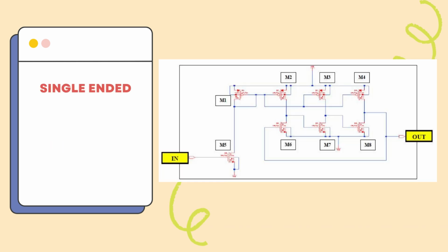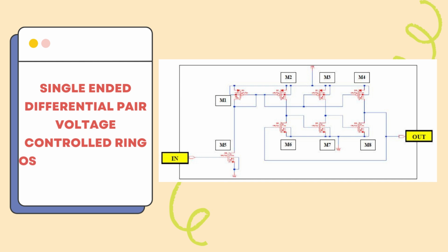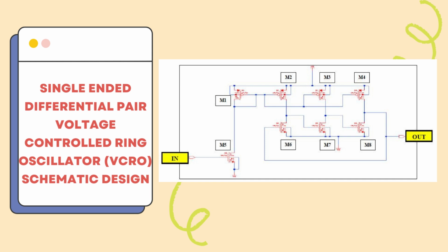Let's now explore the last key component, the voltage-controlled ring oscillator, or VCRO. Looking at this figure, you'll see its transistor-level schematic. This oscillator is absolutely central to our PLL's operation, as it brilliantly converts the analog control voltage it receives from the loop filter into our desired output frequency. We've implemented this VCRO as a three-stage ring oscillator. This design fundamentally involves an odd number of inverting stages looped back on themselves. The propagation delay through each individual stage collectively dictates the overall oscillation frequency of our VCRO.